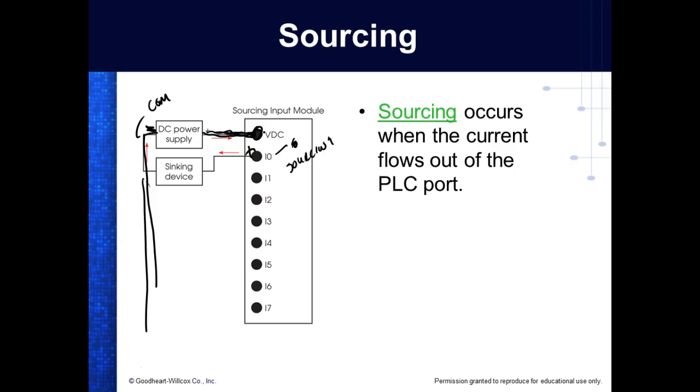Now, like I said, we don't have to worry about this. We don't have to worry about the power supply, right? Y'all understand that? But what I have to do is if it's a syncing input, and I come over here and get the minus, I have to get the plus and run it to all these terminals.